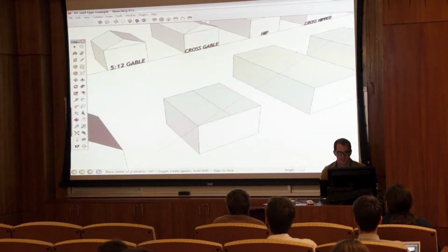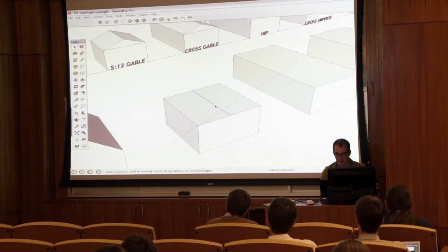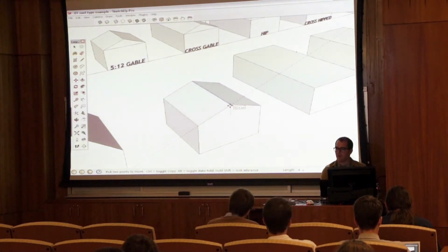There we go. So now we can take the move tool, but I can't just click anywhere arbitrarily to move this up in the blue axes, because it's hard to infer to that edge. What you need to do is take the select tool, select the line, take the move tool, and you need to move from this endpoint here up in the blue axes, and you'll feel it snap when it's on that line.